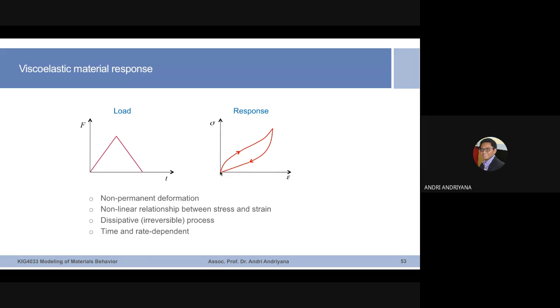If you look at the stress strain curve, it is non-linear. From the thermodynamic standpoint, even though you bring it back to the initial length, the deformation is recovered and is non-permanent. However, certain processes occur in the material which are irreversible. This is characterized by the area between the loading curve and the unloading curve, which is hysteresis.